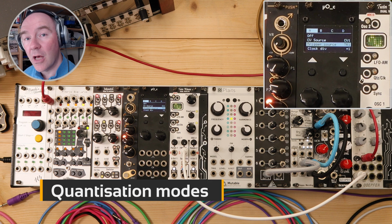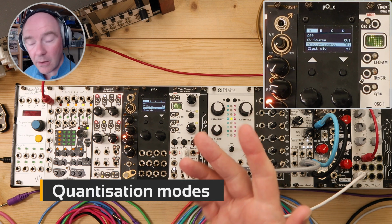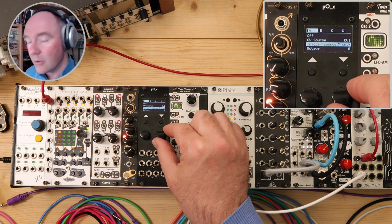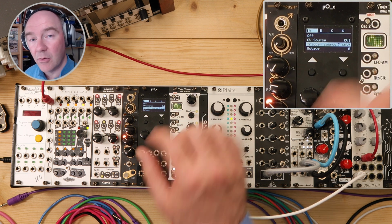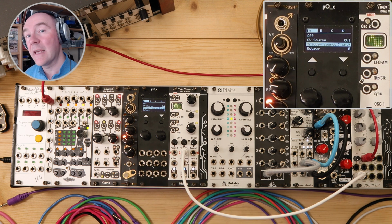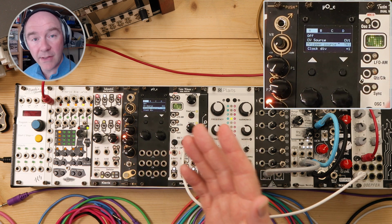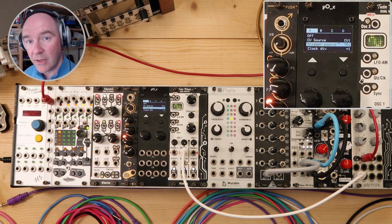Quantization can take place on a trigger, in other words, to a clock, or it can be continuous. You can select the clock source, and you can also select continuous mode. So anytime the input voltage changes, it re-quantizes very, very quickly. All of the quantisers can share the same trigger, or you can have different triggers for each quantiser, or you can break them up whichever way you want.